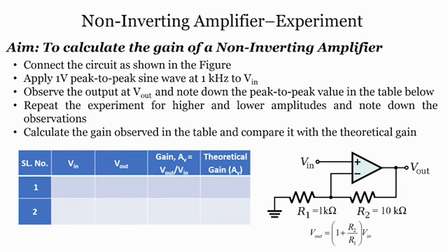First, we have to connect the circuit as shown in the figure. Now, generally when you show this, that does not mean that we are not applying the bias voltage. Even if it is not shown, it is assumed that a bias voltage, plus VCC and minus VEE, is applied across the terminals. Plus minus 15 we have applied. Even if you see a circuit where this is not given, that does not mean VCC and VEE are not given, because without bias voltage you cannot operate the amplifier.